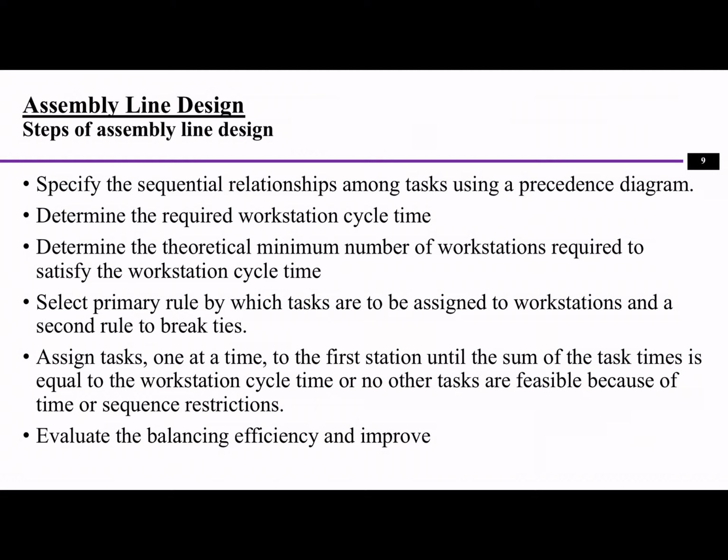If it is a really low cycle time, then we have to figure out how to design this line in order to reduce that, right? But sometimes it's not really that critical, then you can probably lift the restriction a little bit in order to achieve some other functions. So the cycle time is important for determining the assembly line design as well.